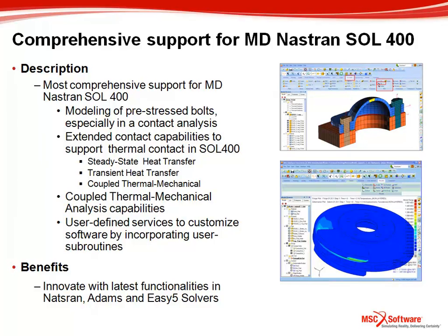SimXpert continues to be a comprehensive support solution for MD Nastran Solution 400. So support for pre-stressed bolt analysis, especially in contact situations. We have extended contact capabilities to support thermal contact in Solution 400, and this includes steady state heat transfer, transient heat transfer, and coupled thermal mechanical capabilities, which are now supported in SimXpert.